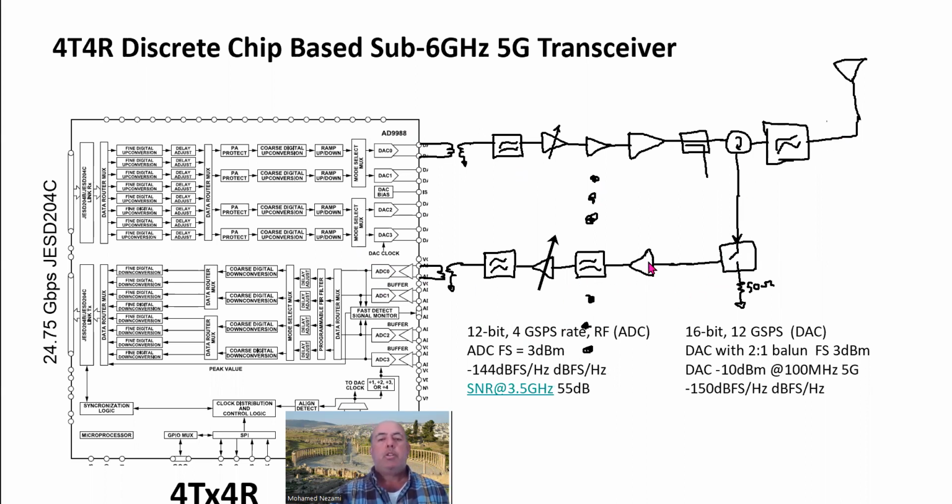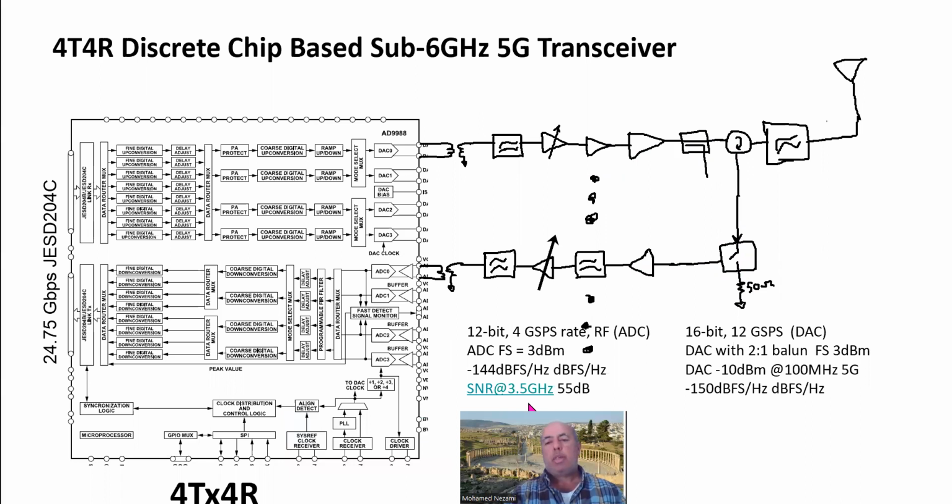And then you start, of course, distributing that. You've got losses, you've got the balun loss, you've got the copper loss throughout, you've got filter losses, and then you've got the switch loss. This switch in here, we utilize it so that when we transmit, we put this switch into 50 ohms, so you're terminating any reflections or any leaking from the transmitter into the 50 ohm instead of going into the LNA, which is a sensitive device. You don't want to damage that. So that's what that switch is for. So here's some loss, and of course, don't forget the losses in the front end filter and the circulator.